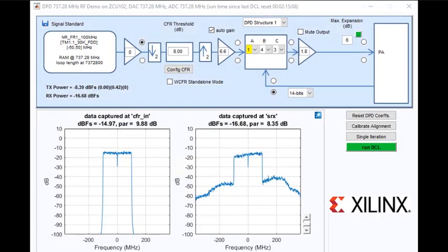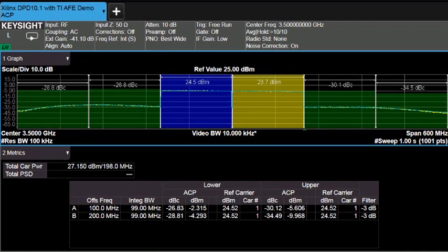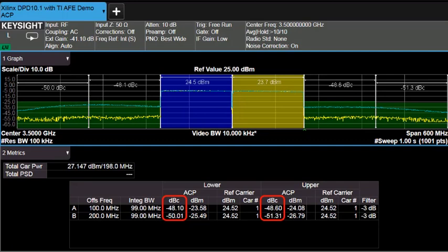And finally, we will use our NR carriers, in this case 2 NR100 carriers, to look at the performance of the PA with the 5G signaling. Again, we activate the DPD here, and if you look at the trace on the right-hand side, it's the output of the PA, the feedback path, and you can see the linearized performance of the power amplifier. But let's take a look at the signal analyzer. So there are 2 5G carriers there, 100 NR carriers. Now we will activate the DPD, and the yellow trace will show the corrected performance. And again, as highlighted, excellent adjacent channel power performance.